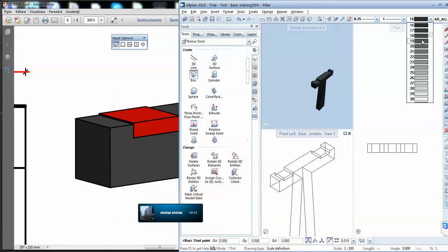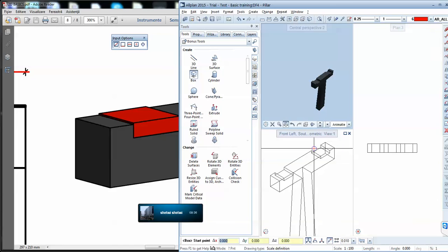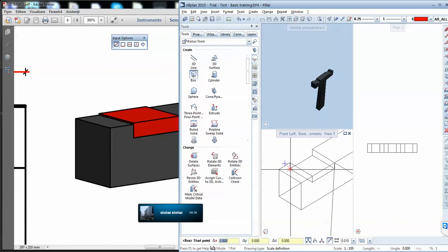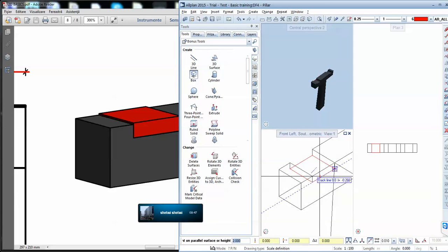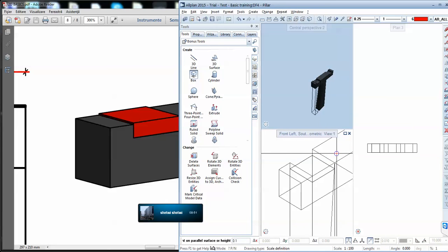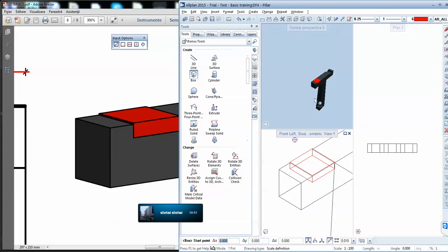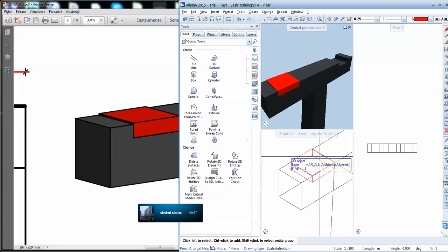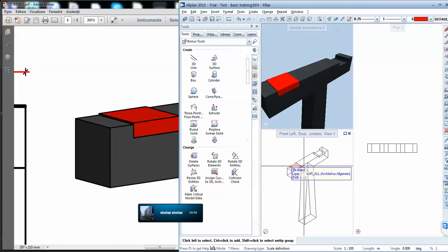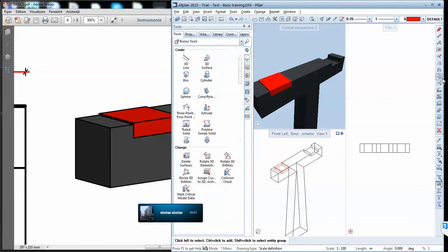And also, in order to have the same colors, I choose red here, and then select first the base through 2 diagonal points, and then on the height of it I can indicate a direction and say it's 0.1. So it will be 1 centimeter above the concrete part. And then after I create this 3D object, I can use the usual functions.